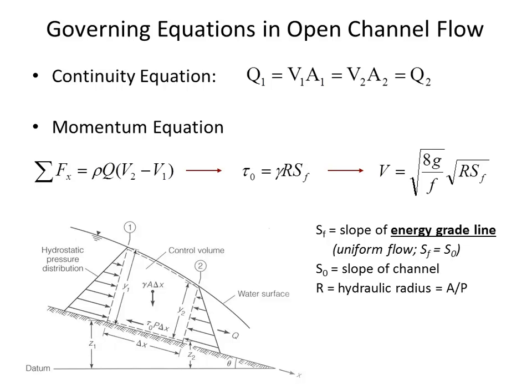Just the very end of the flow, like flow is just filling up the channel. Maybe it looks like that. Okay, so you're saying that if the flow rate was increasing, like if it was deeper on the left, this is like a wave that's traveling downstream. Okay, that is a possibility, absolutely. So it could be that not only is it non-uniform, which is what we can see from the picture, but maybe it's also unsteady. In the case that he describes, unsteady flow would be somebody opening up the gate of a dam or something, and so there's this big surge of water coming downstream.